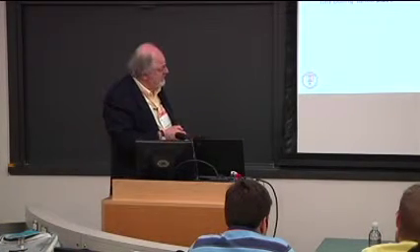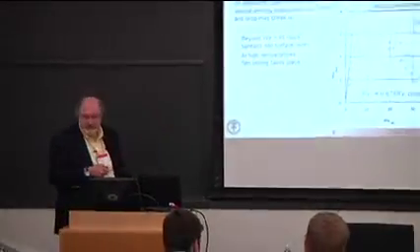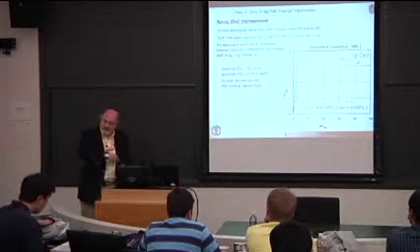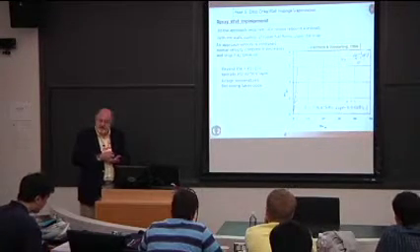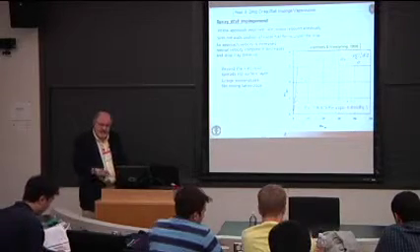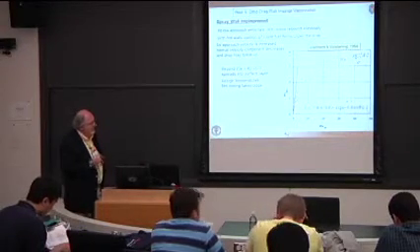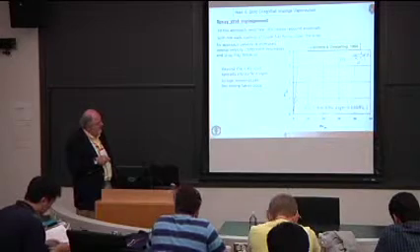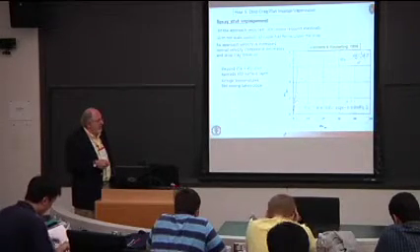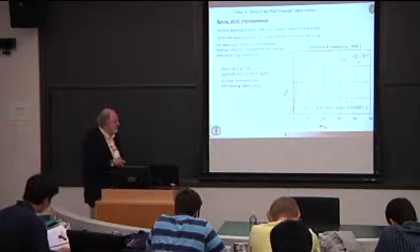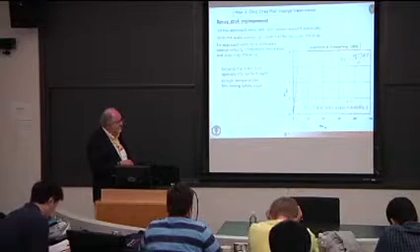And what this says is that at low values of incoming droplet Weber number, the droplet bounces off the wall with Weber number out equal to Weber number in, which is this straight line here. But as I increase the Weber number of the incoming droplet, some energy is dissipated during the interaction with the wall. The droplet flattens and basically loses some of its kinetic energy. And so I don't follow the elastic bounce curve anymore. In fact, I reach a maximum, and then eventually the outgoing droplet doesn't even leave the wall. The liquid spreads across the surface of the wall. So the outgoing Weber number goes to 0.